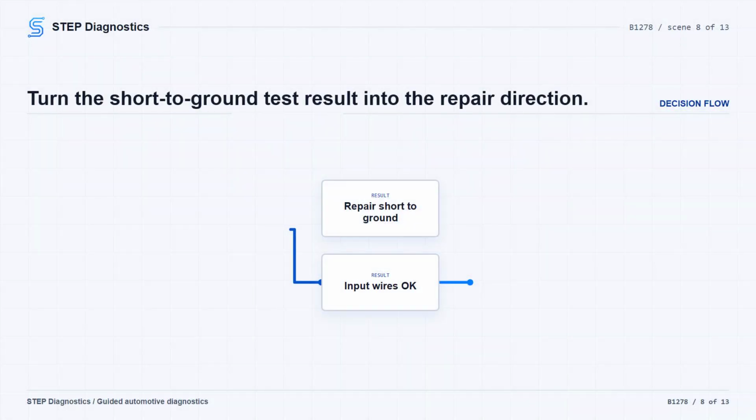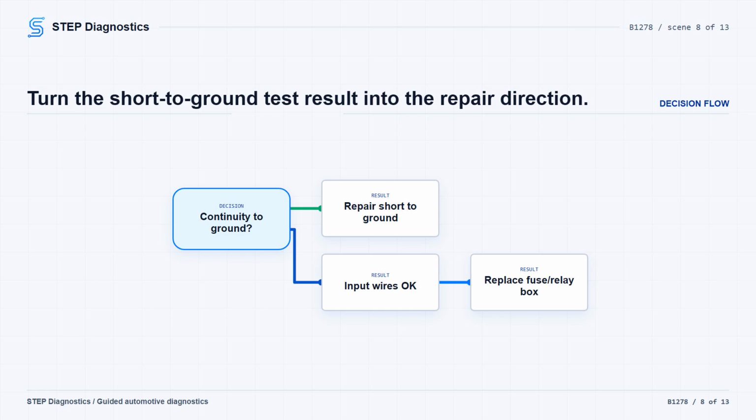Check H/L on SW from connector N no. 19 YL to body ground. Check parking LT SW from connector N no. 20 GRI to body ground. If there is continuity, repair a short to ground in the wire. If there is no continuity, those switch input wires are okay and the path identifies a faulty MICU. Replace the under-dash fuse/relay box.